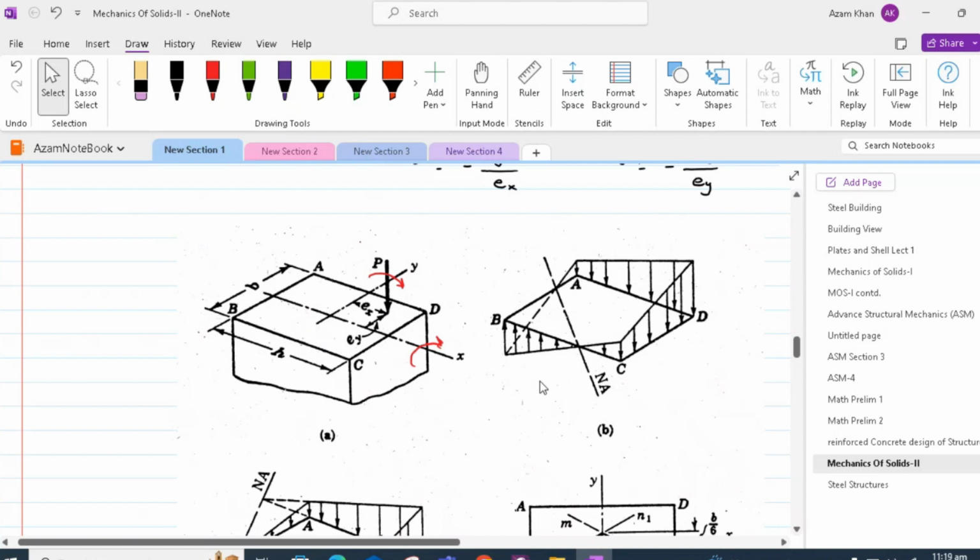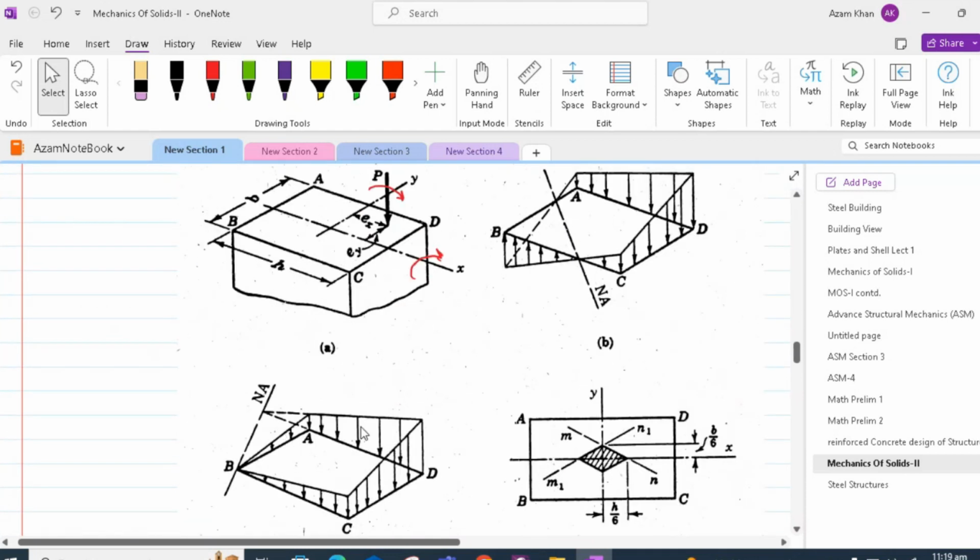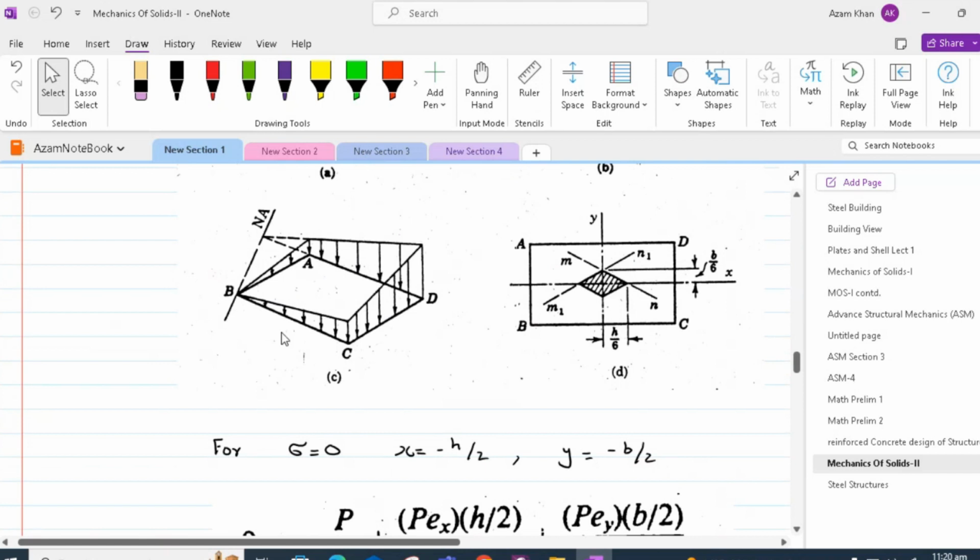It is due to this reason that the quadrant opposite to the applied load P will be subject to some tensile loading. In order to ensure that the full cross section is under compression, we will have to apply the load at such eccentricity that this neutral axis is at most moved to point B as shown in this figure.